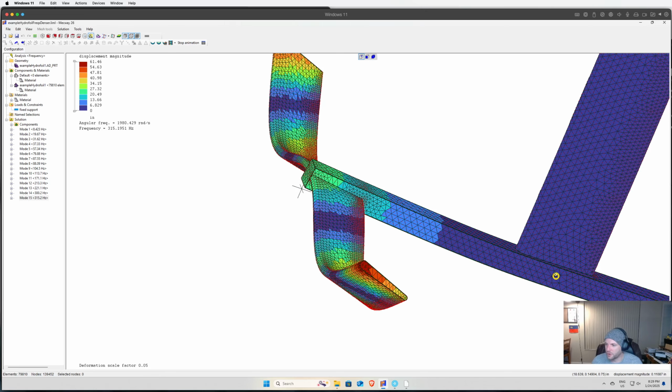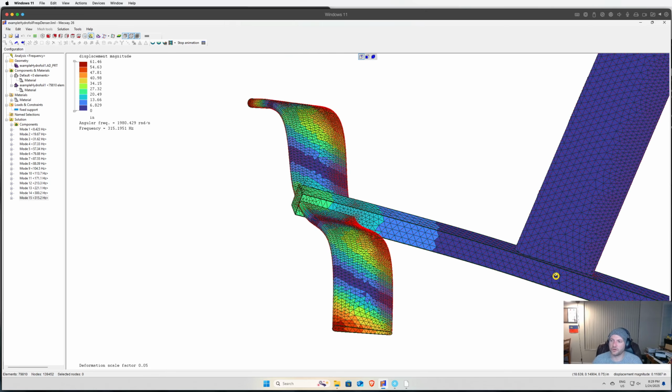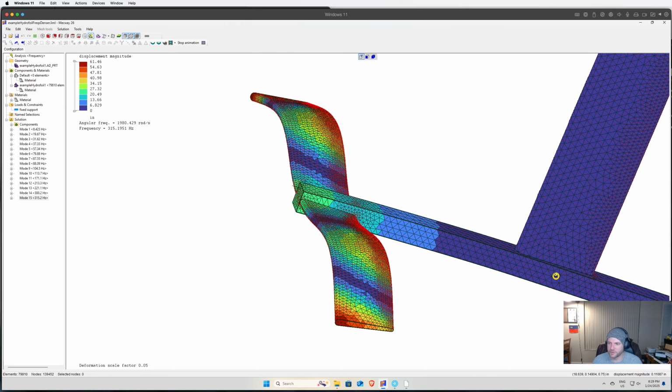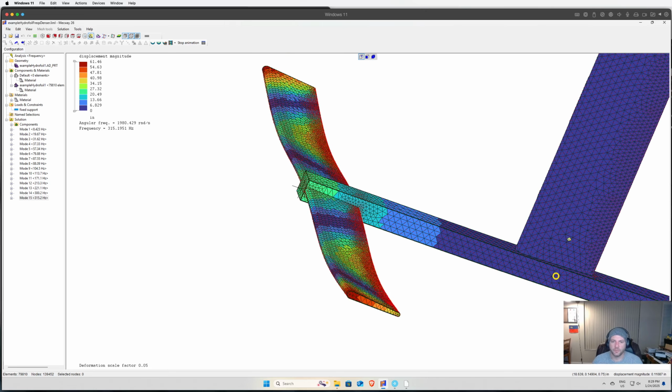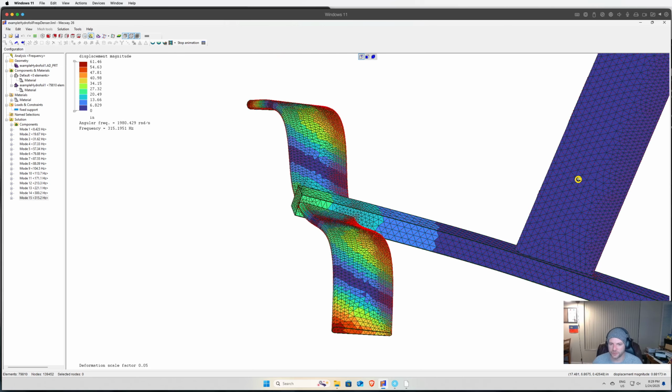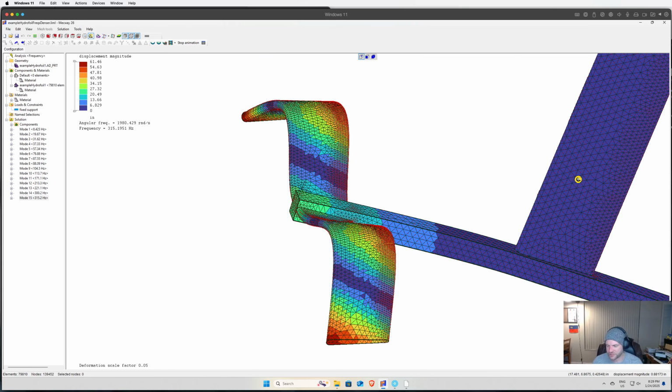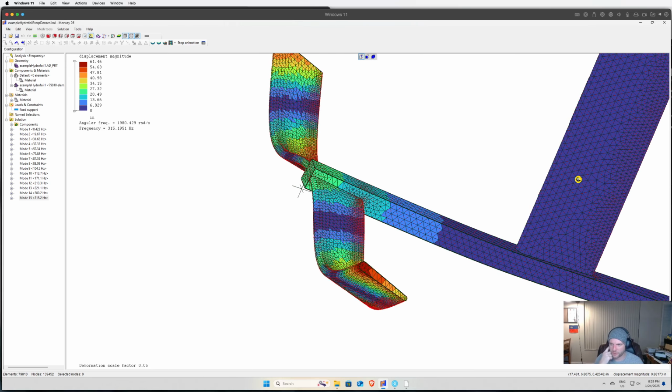That's when you really need to know the loads. You need to know if the fasteners are going to work right, if the load is passing through at the joints, where the joint design becomes important. I think that really starts to matter. But for the gross deformation of things, stiffness just dominates the equation. Just, are you even in the right ballpark of this thing? And you need to solve the stiffness problem first. That's almost always the case.